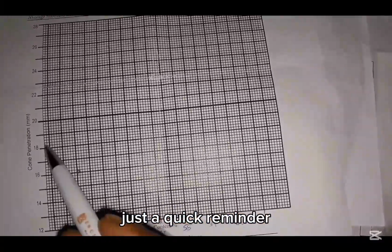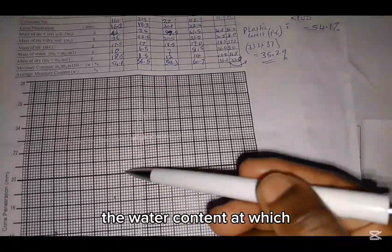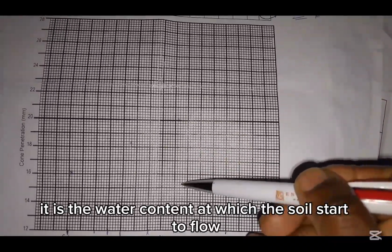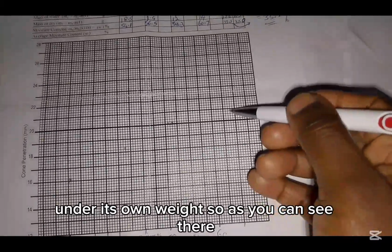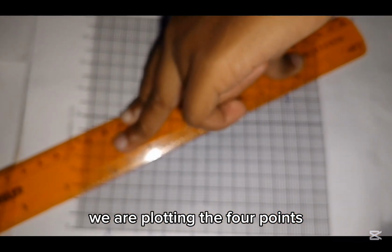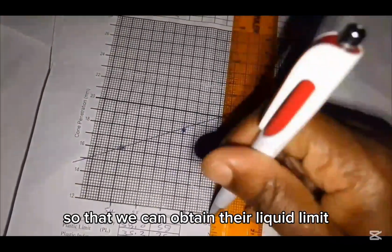Just a quick reminder, our liquid limit is the water content at which a soil changes from a plastic state to a liquid state. In practical terms, it is the water content at which the soil starts to flow under its own weight. So as you can see there, we are plotting the 4 points so that we can obtain the liquid limit.